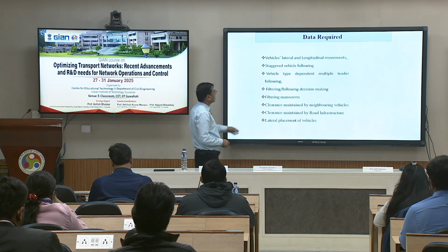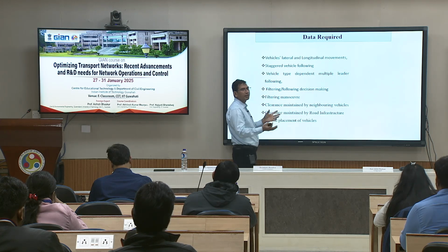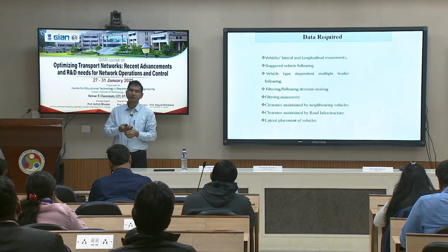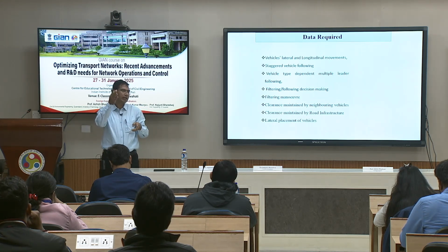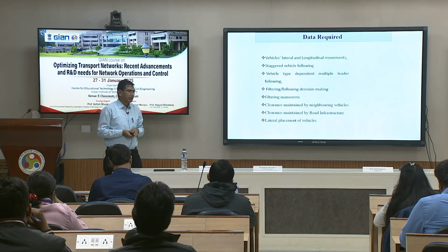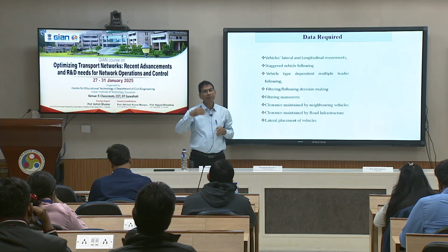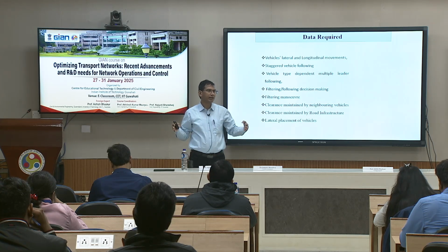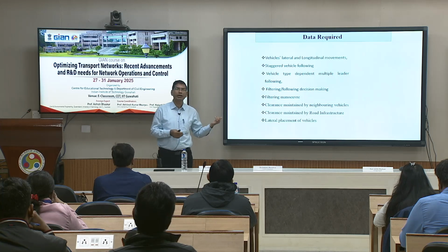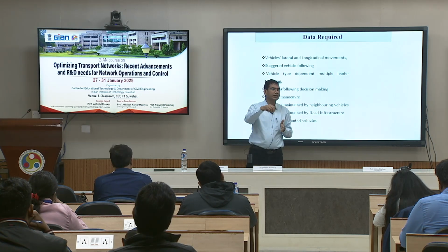These are the behaviors which should be present in any traffic model for the Indian traffic context. In order to study all this, a lot of parameters are required. How do we get those parameters, because you require vehicle position, and each and every vehicle's speed and acceleration altogether. If you require this long list of parameters, it is always better to have very basic data which can lead you to any type of parameter required for studying this kind of behavior. That is vehicle trajectory.